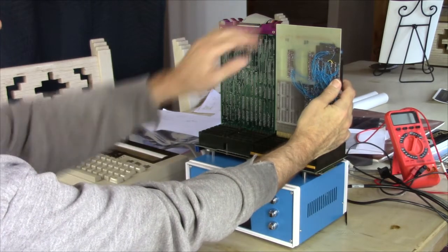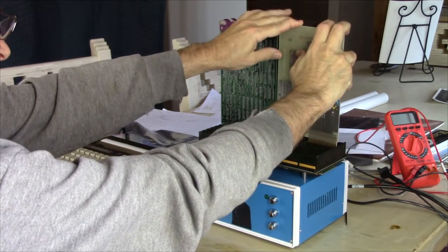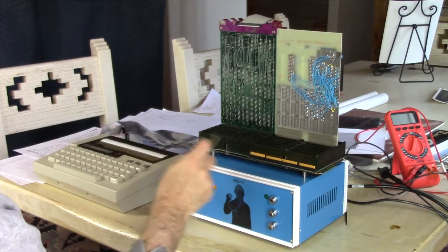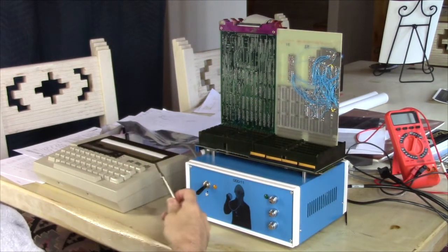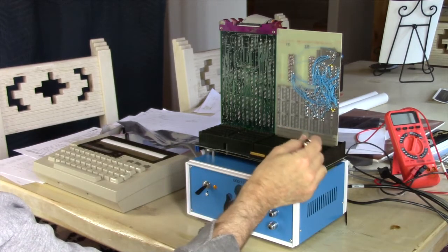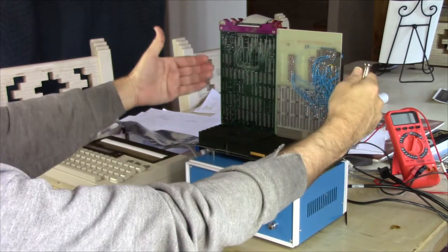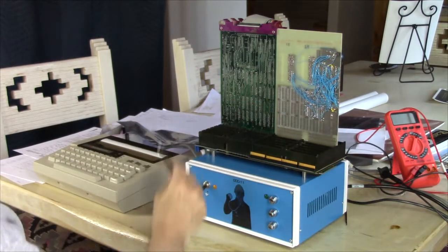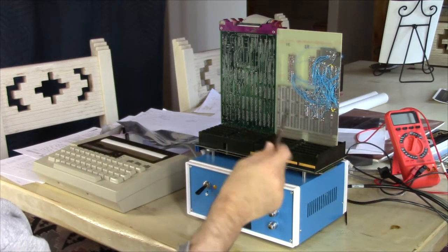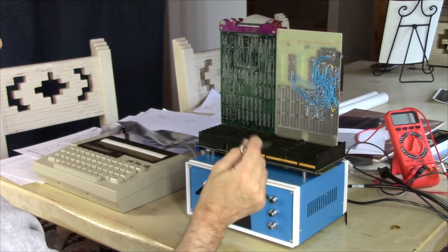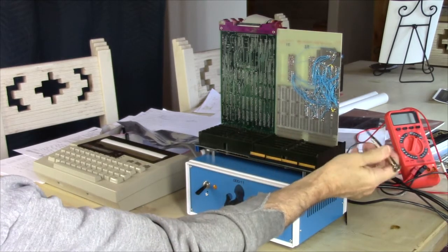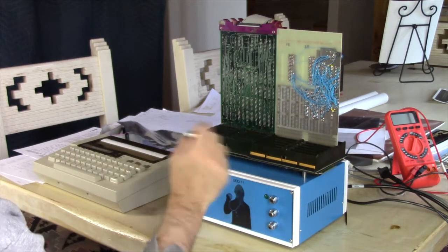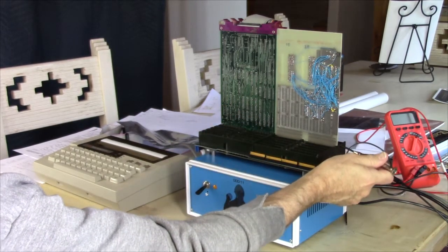And bus slots, oh well, that's an interesting concept on the Q bus. There are two kinds of bus slots. There are the ABs, which is what your regular cards plug into. And then there are the CDs, which is, well, some cards are for quad width. These are dual width. But the CD bus is just used. So AB is the Q bus, and CD has a sort of little private bus.